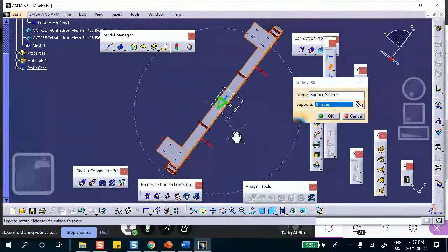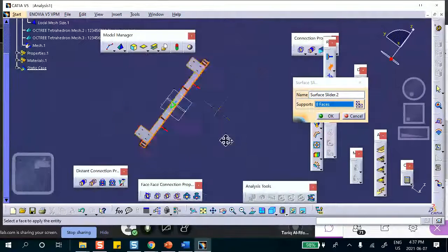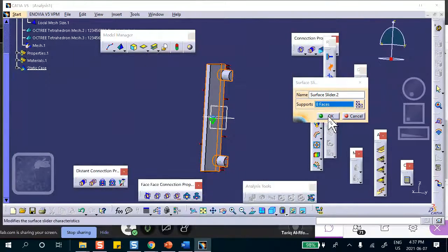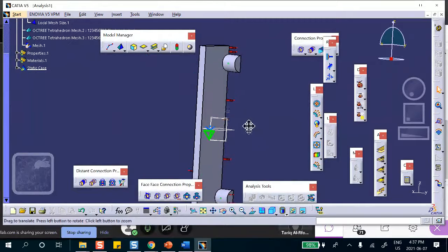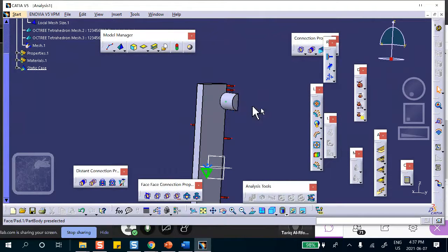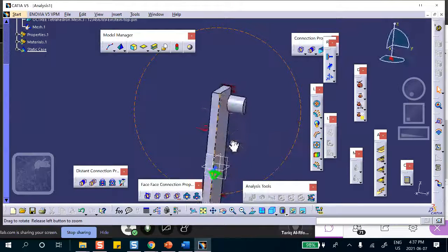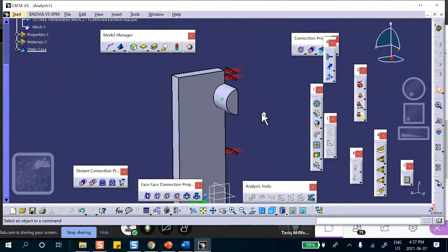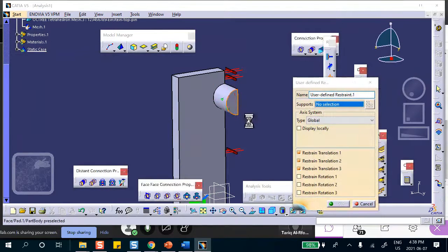These are all surfaces that have been introduced because you claim that it's a plane of symmetry and you made a visual cut there. Good. Now, this guy cannot move out anymore. Remember, it was moving out because you put surface slider here, it cannot move out. So some of the problems that we ran into are not going to happen anymore. So, for example, this edge, all I have to do is to go, hey, move up. That's all. It won't come this way. It won't go that way.